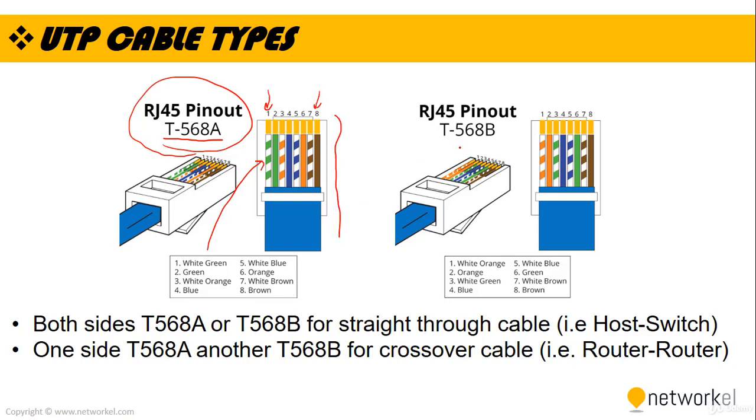If you're using T568B, in the first pin you're using white-orange cable this time, then orange, white-green, blue, white-blue, green, and white-brown, and the brown.